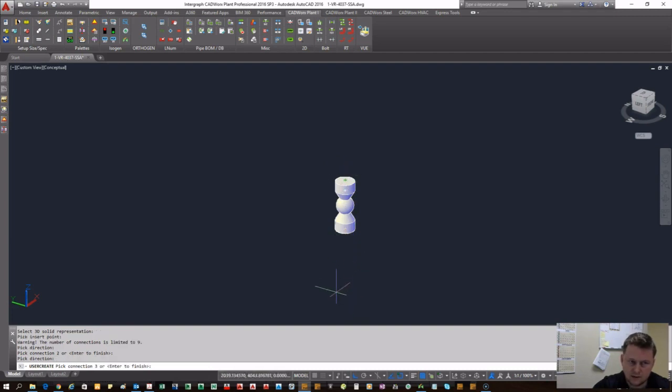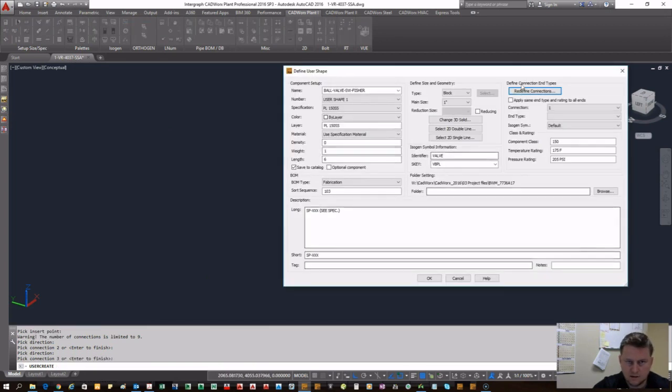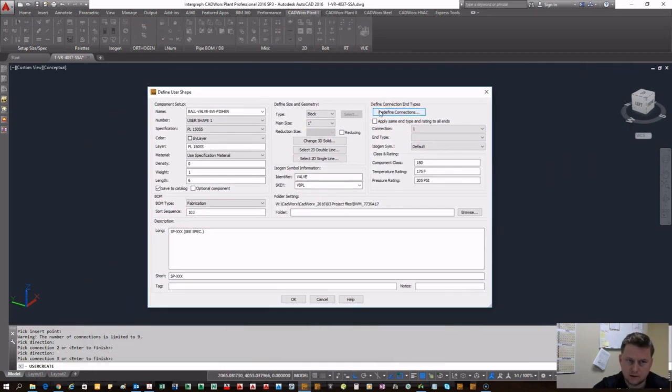So click it, and then you indicate the direction that you're coming from. So you're never going to come into the component. You're always going away, as if you were piping away from the component. Which way would you go? Okay, so after you've selected all the points that are intelligent, right click. Okay, there's one more step in this process.